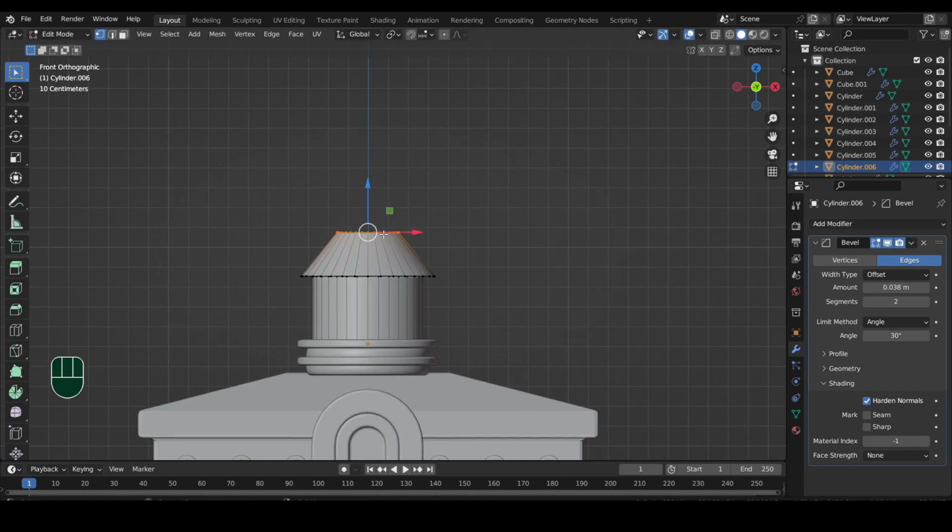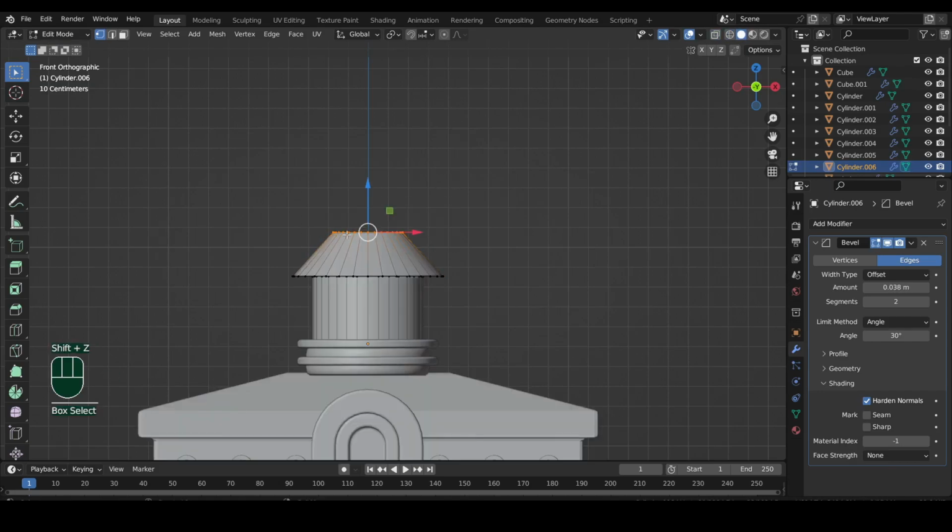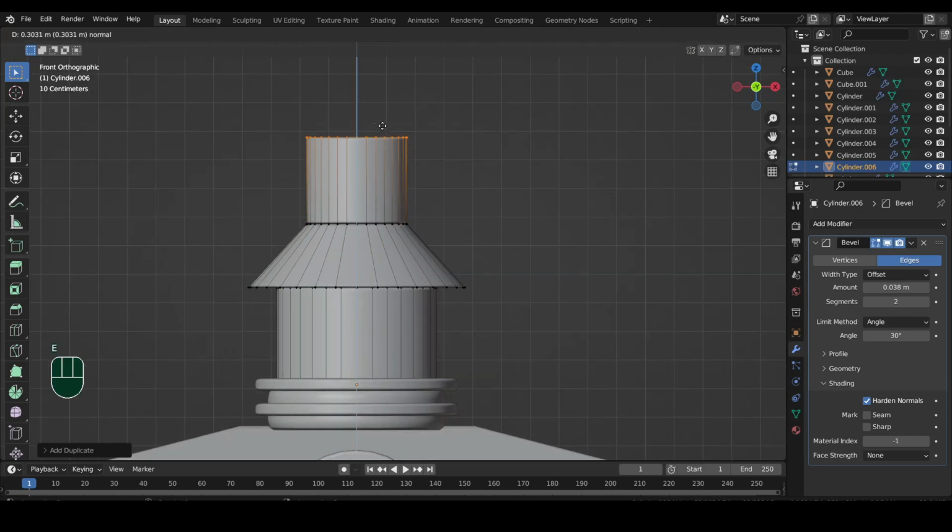With any part of the object selected, press L to select the whole connected mesh. Then scale that up a bit on X and Y axis. Again select the top vertices. Make sure you are in wireframe when you do that. Duplicate and right-click. Then E to extrude up.